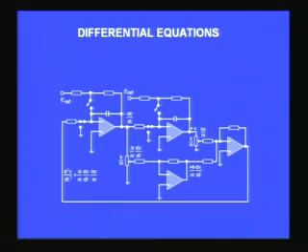When I do a solution, you find the solution mathematically, analytically. I will get the solution after performing certain mathematical manipulations, and if I want to change some of the variables or the coefficients, then I have to almost start all over again and obtain the solution once more. Here all that I have to do is modify some of the voltages or the coefficients b by m or k by m factors, which by using potential dividers I can quickly change for a new equation and then implement that in a moment's notice, and then try to understand how the stability of the oscillator is, what the damping ultimately leads to, and things like that.